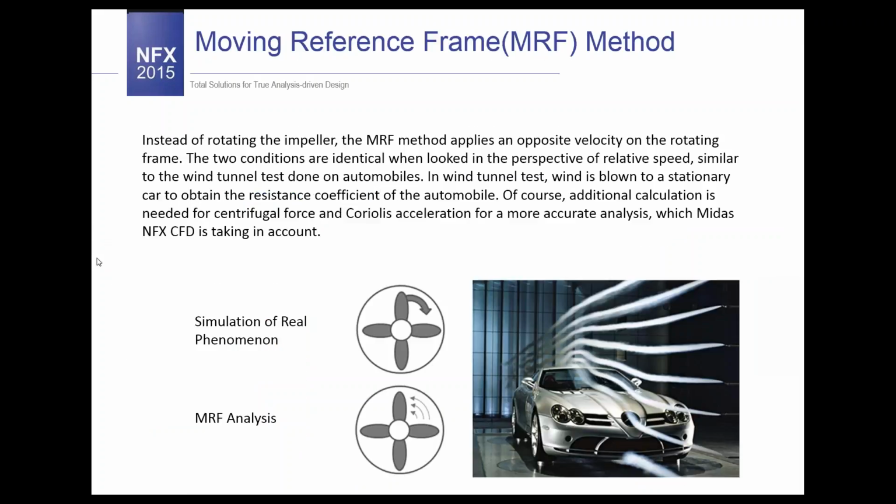Now we are going to the second part of this webinar today, which is about the moving reference frame method, also called MRF. Instead of rotating the impeller like we did at the beginning, MRF is a bit different. It applies an opposite velocity on the rotating frame. The two conditions are actually the same, but from the perspective of relative speed. You can look at this photo, for example.